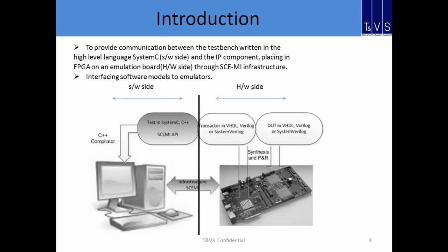What SCE-MI does is provide an interface between the software and hardware. The software part is the test bench written in a high-level language like System C, and the hardware is the DUT placed on an FPGA on the emulation board. Those two are connected through the SCE-MI infrastructure.